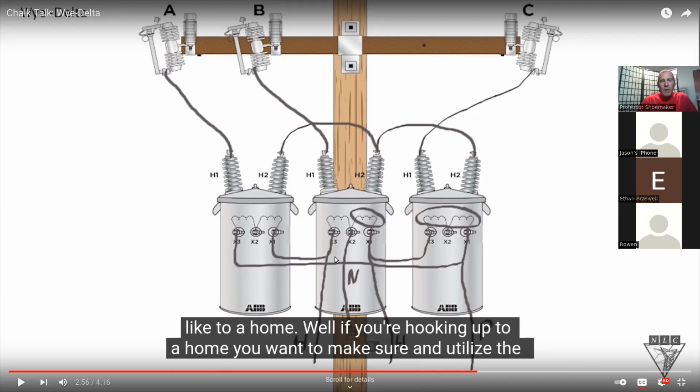So, you know, he cheats here a little bit. Instead of carrying two wires down, one from the left transformer down to make a connection, and one from the right transformer X1 down to make a connection, he just puts a jumper across here, which in real life is what happens. We don't do it in front of the transformers.